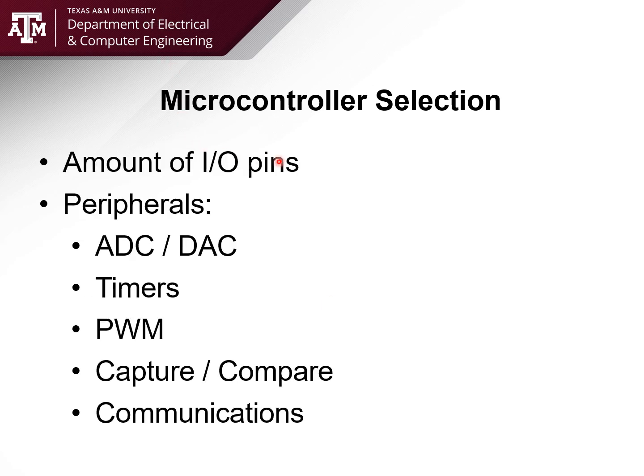Then you always have to consider the number of I/O pins. Always err on the side of more pins is better. Don't just choose the number of I/O pins to match your particular solution. If 10 I/O pins is all you need, look for a device that maybe has 20, because as you're redesigning your system, you might want a few more I/O pins.